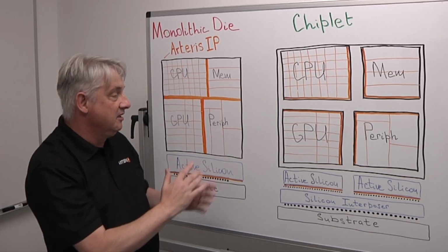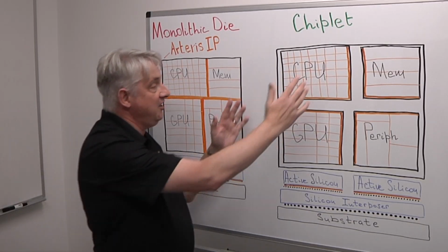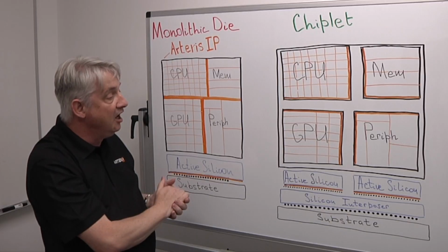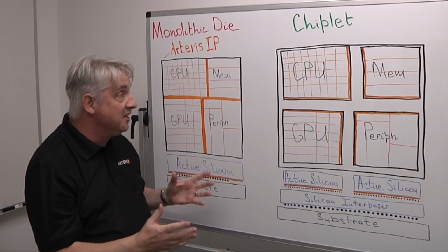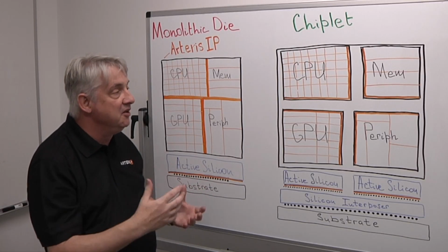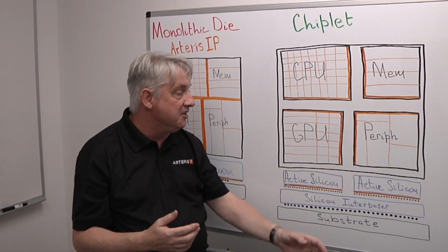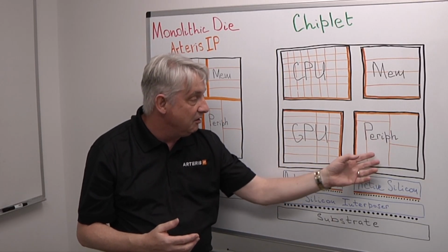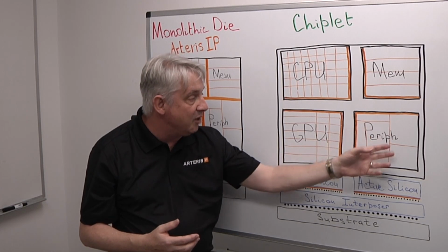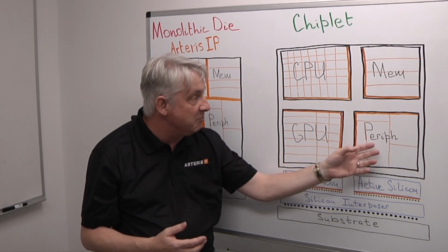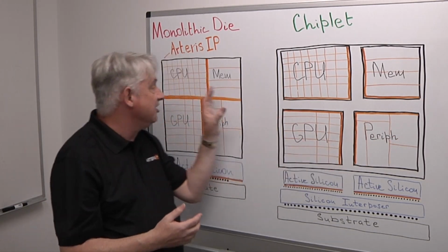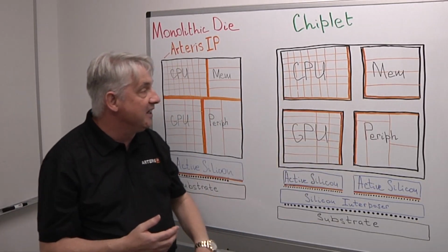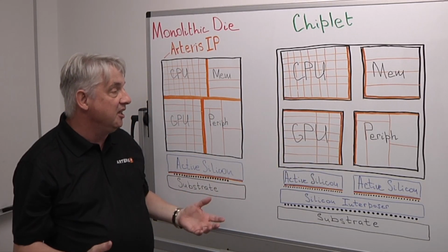Now, agreed, to make this whole solution is going to cost you a bit more than this, but you have much more flexibility in terms of how you develop it. So you can build a system with different sizes of memories or different peripheral blocks according to what you need in the design, and these are much quicker and cheaper to redesign than this whole thing. So you can spin the designs much more quickly according to your requirements as they change.